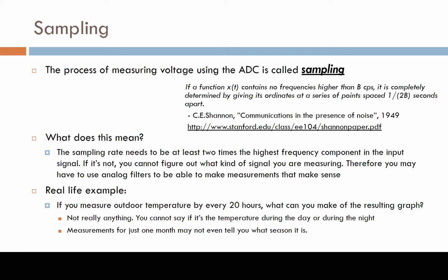And actually, before the sampling, you should either have a high enough sampling rate or filter out these too high frequency components. If you are sampling with high frequency components, then you are bound to have big messy data. No doubt about it. It happens always.